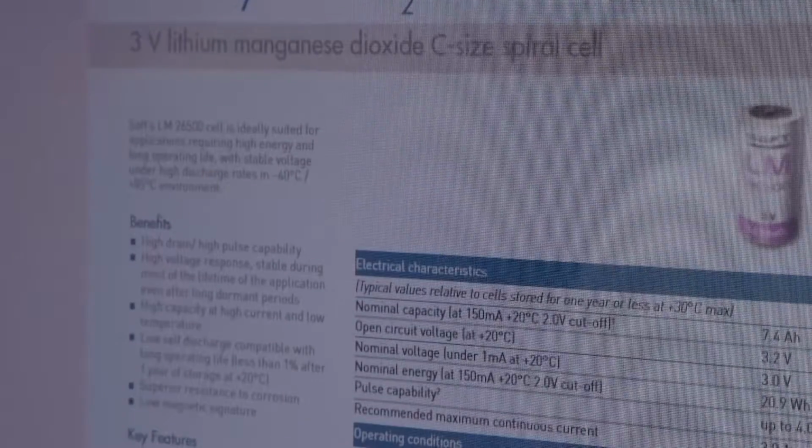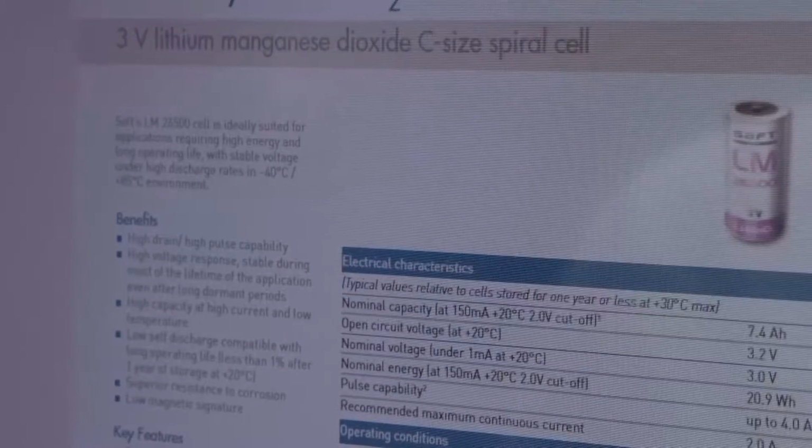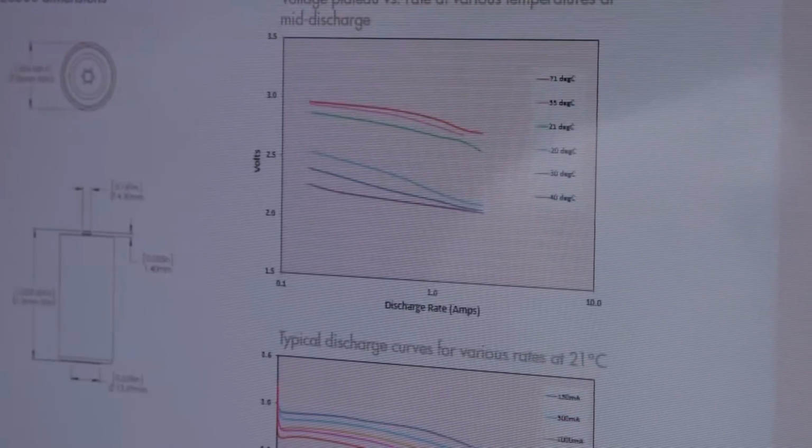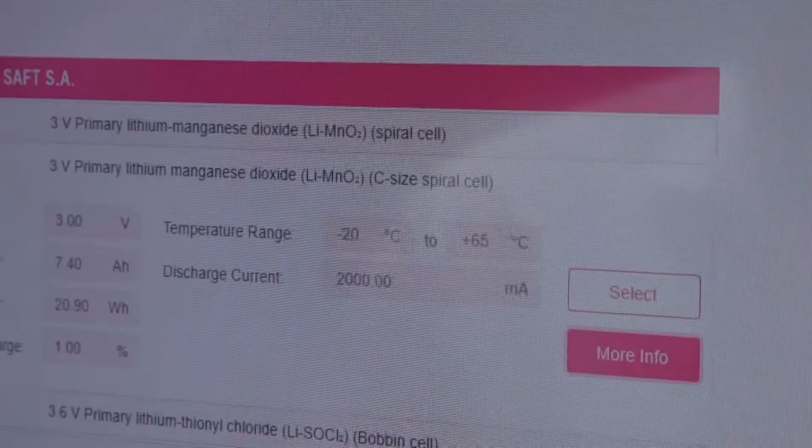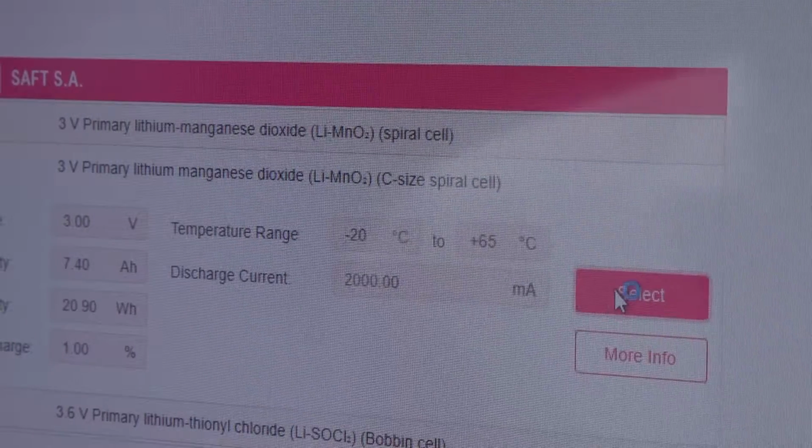The next step after doing that is you configure the rest of the power consumption. You see, most of the power consumption is not actually happening in some cases inside of the module. It's all of the rest of the hardware. So the MCU, sensor, power consumption. We actually have all the data of all the projects, and we can give best practice implementation guidance to customers in case they're not sure what to put here. But usually device suppliers, they have a pretty good idea. Once you enter in, for example, the average current consumption in wake-up mode and sleep mode, then you can proceed next to select the battery.